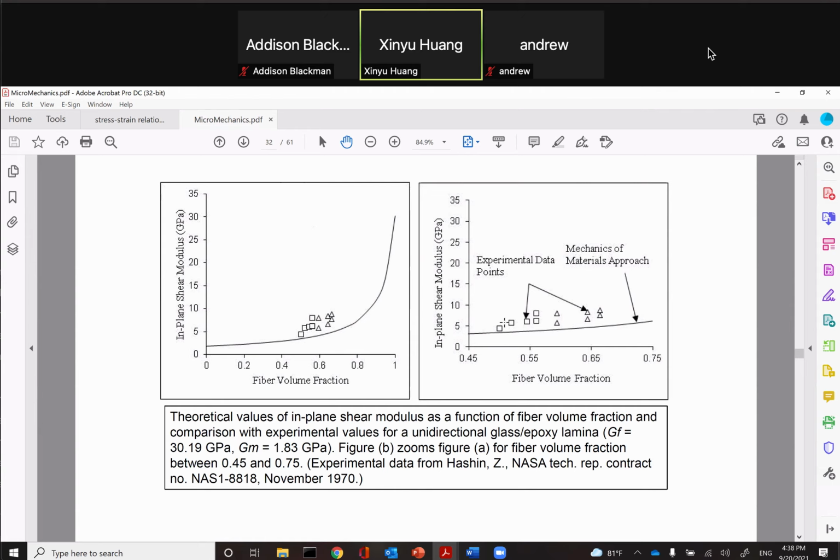So let me share with you some of the experiences when you want to predict material properties. There are several classes of properties. When you get in the job, people ask you to predict certain material properties of a composite, whatever it is. If you're asked to predict modulus, which means the stiffness or things like that, usually it's easy, and you can get pretty close. And then if another day someone asks you to predict the strength, the breaking load, it gets difficult.